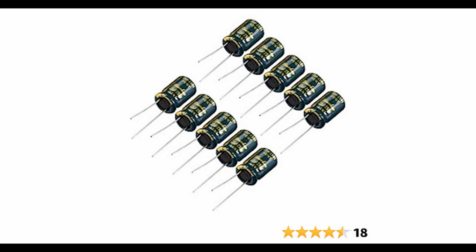Tantalum electrolytic capacitors. Tantalum capacitors have relatively smaller capacitance values compared to aluminum electrolytic capacitors. They usually range from a fraction of a microfarad to a few hundred microfarads. Tantalum capacitors are often used in applications where space is limited, and higher capacitance values are not required.